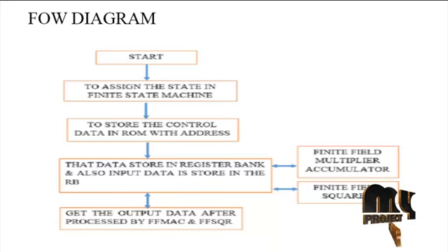This FSM has 4 states A, B, C and D. The system has one input signal called P, and the value of P determines what state the system moves to next. The system changes state from A to B, B to C and C to D as long as input P is high. If P is low and the system is in state A, B or C, the state is not changed. If the system is in state D, it changes to B if P is high and to A if P is low.